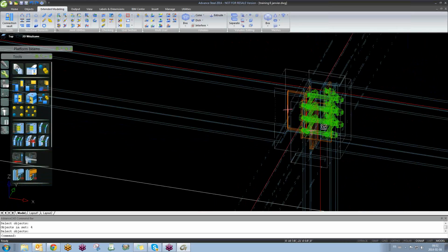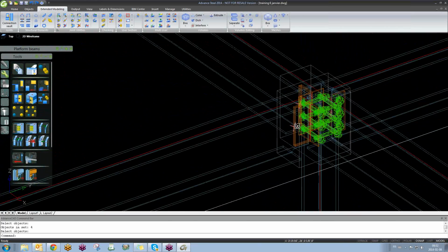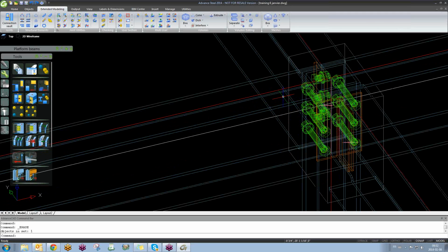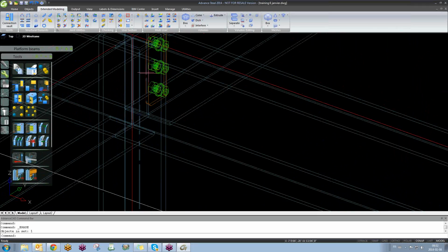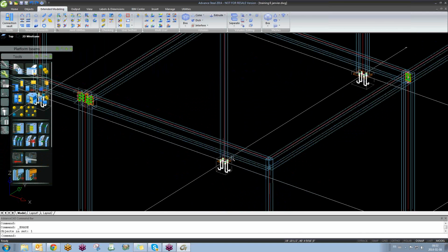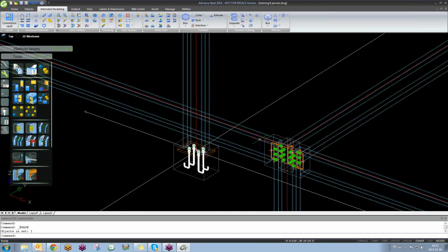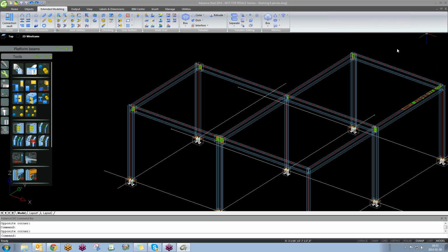Well, in here it's not really the right thing to do. It's not the right connection. Okay, we'll delete it from here, and here. From here neither. So, do you get the point, guys? Yes. You have to select the columns first, hit enter, and then all the beams, enter. That will do the job. Okay. Do you want to try it, guys? Yeah. Okay, we'll give you 3 minutes for that.